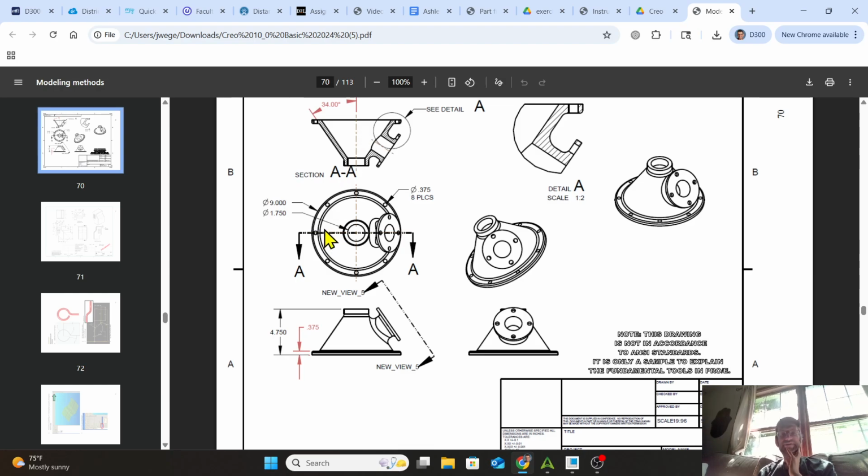It also shows us the direction at which we are looking at that part when we're viewing the sectional view too. So since this part, we're looking at the top and we're rotating that thing 90 degrees around down towards us, the arrow shows us how we'd be looking to see this upper view here. It's a little less clear on a view like this where we're rotating things around and we have it placed a little bit oddly at the top there.